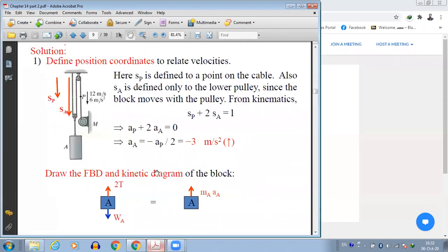The thing is that this body A is moving up, and its motion depends upon the power with which the rope is being pulled by the motor. So it's not a free body motion, and we cannot take the acceleration as 9.8. For acceleration to be taken as 9.81, it has to be a free body motion. It's not being held by anything, or governed by any other motion.